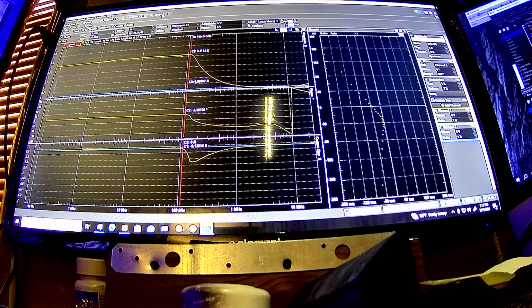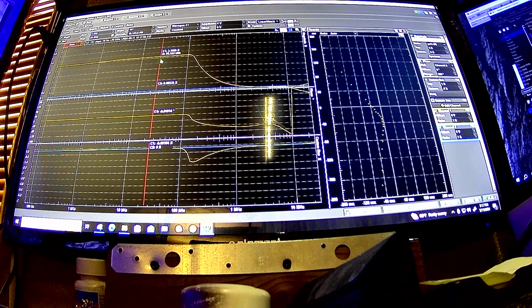but it's better than farting around with a scope and the frequency generator and trying to adjust it until you see the waveform start to decrease. Like I said, normally I don't use it at low signal levels, because oftentimes you need to have it at low signal levels. If you're doing a gain of 10x amplifier, you probably wouldn't want to put any more than a volt across it, because that'd be 20 volts peak to peak.